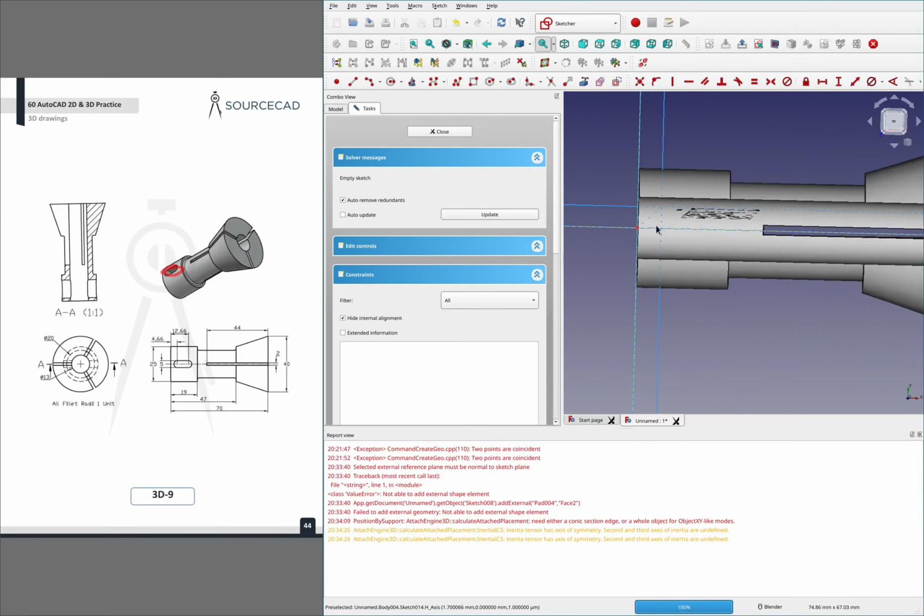I'll cut and grab the pocket tool, I guess slot tool, and our slot is 5 tall, so dimension this at 5, and then center to, let's see, yeah, so we've got the 2 sides of the slot dimensioned individually. So that should be relatively straightforward.